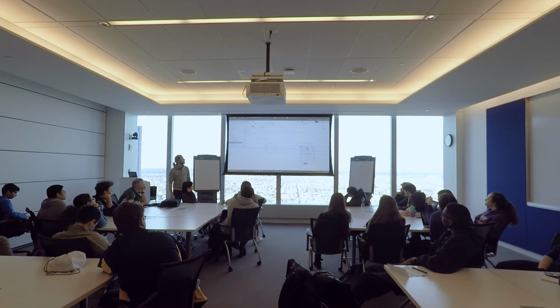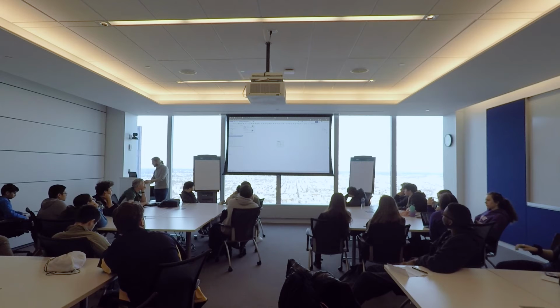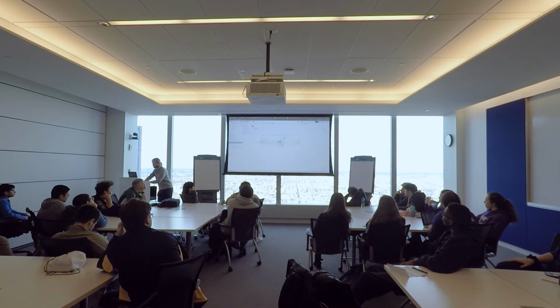So again, this was really quick. Notice the 34 is the base length, same thing. So I can now come into this model, and if I say, okay, maybe 34 is not quite long enough, maybe we want it to be 36, I can come into here and it automatically changes my length to 36. And it just sets up the model really easily.